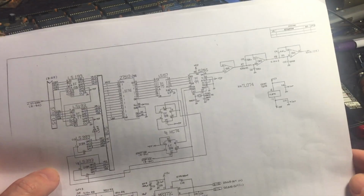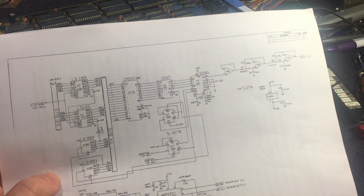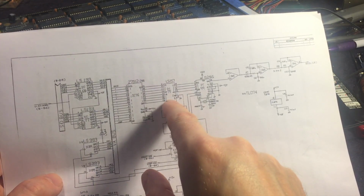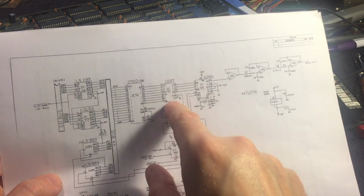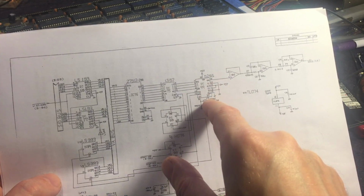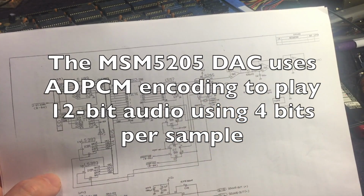And then there's also what they call a voice section, which plays pre-recorded samples. And that is done with some counters, a fairly large EEPROM, and a mux that flips between the bottom and the top 4 bits of the 8 bits from the EEPROM and sends them to a specialized DAC that takes the 4-bit input and converts it to a 12-bit output.